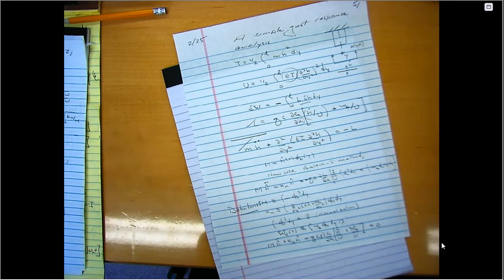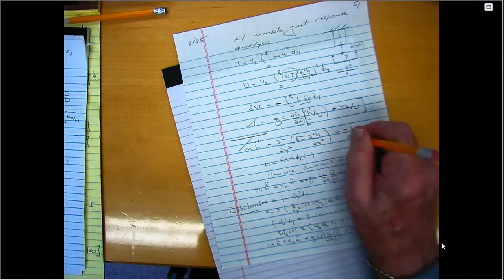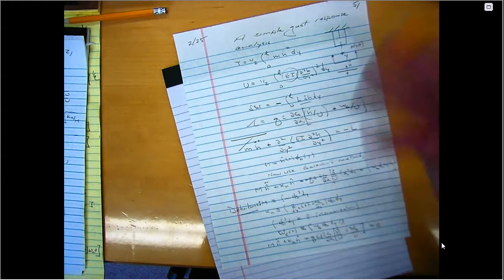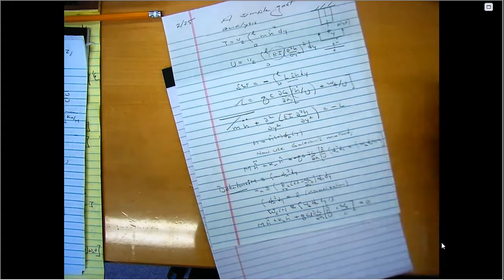In fact, in homework number 7, you're going to include not only this equation for H, but also the dynamic equation for alpha. You're going to do bending of the wing and torsion, because I need both bending and torsion in general to do Fourier analysis. In gust response analysis, I can often physically ignore torsion and still get a decent answer. And obviously it simplifies the model.